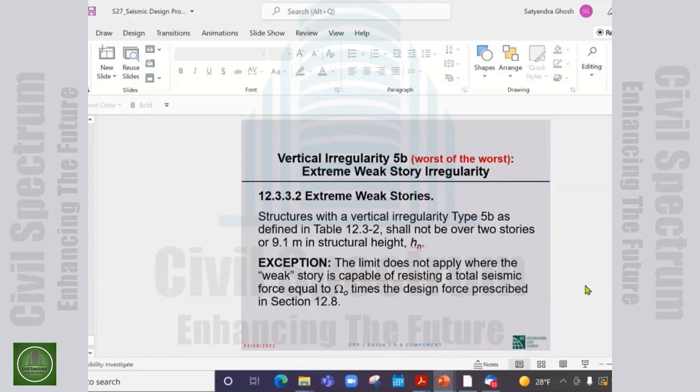The response modification factor will be, that is a good question. I would tend to take something like, let me think for a second. As the openings get smaller and smaller, you tend to approach a shear wall core, and that would be an R of 5.